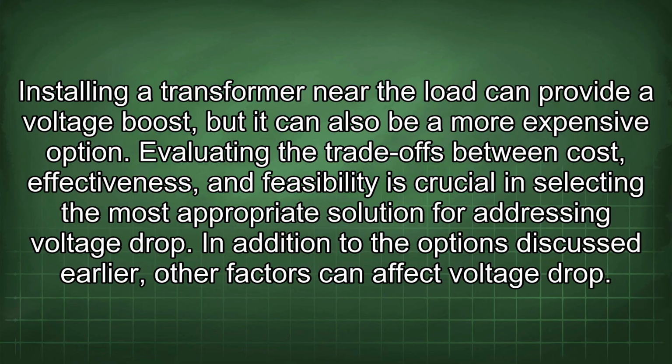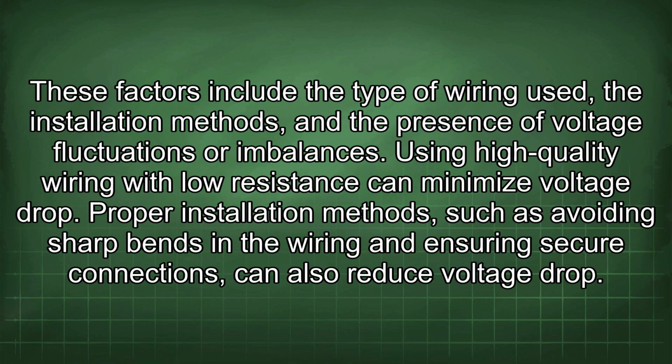In addition to the options discussed earlier, other factors can affect voltage drop. These factors include the type of wiring used, the installation methods, and the presence of voltage fluctuations or imbalances. Using high-quality wiring with low resistance can minimize voltage drop.